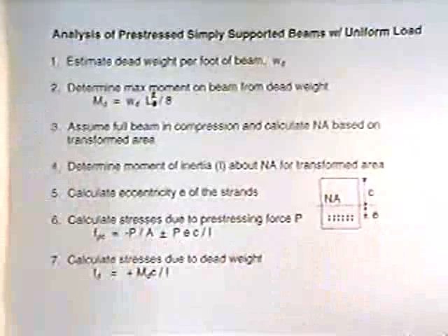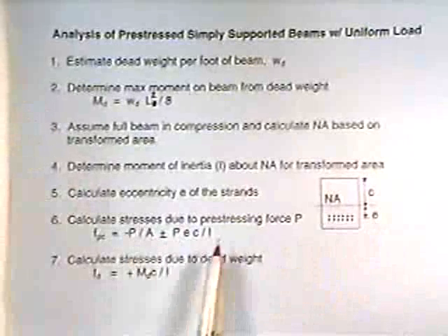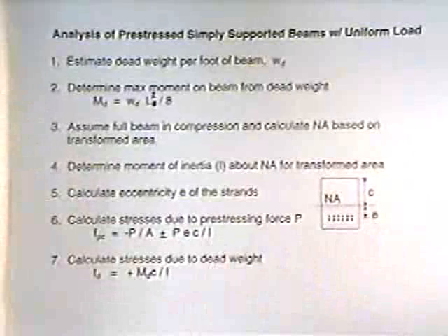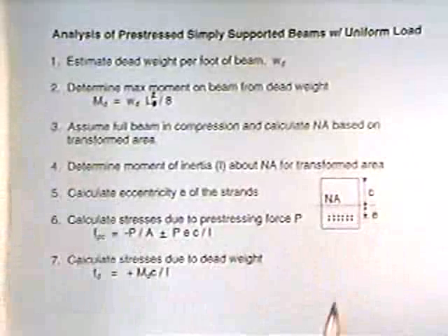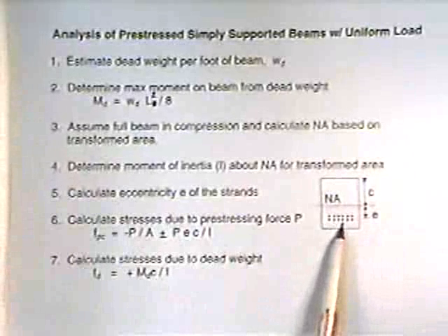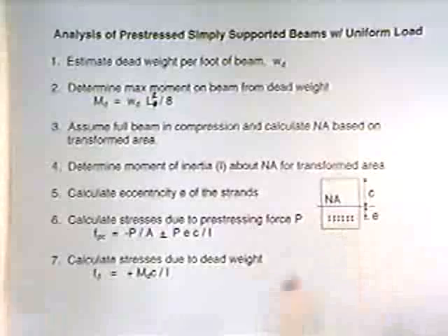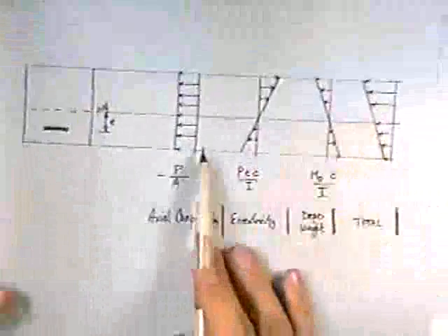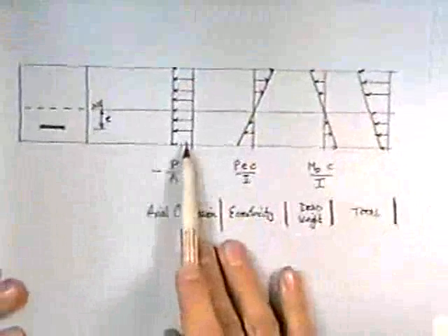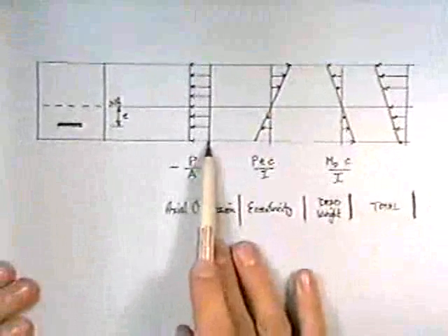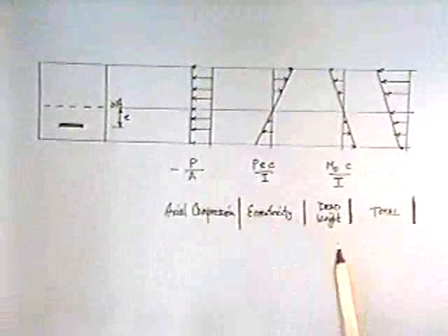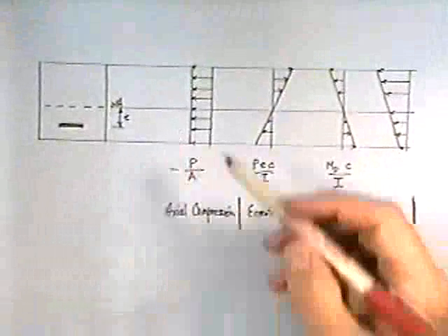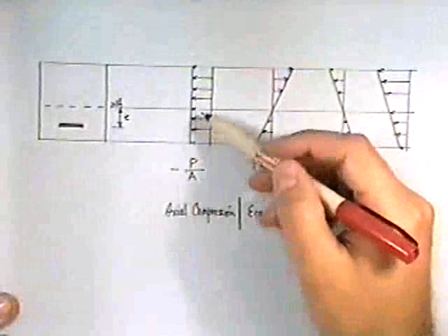Now what about stresses? The stresses that are going to occur are 3 of them. Just imagine that you post-tension these rods. What are these rods going to do? They're going to try and squeeze the concrete beam together, in a uniform distribution. You guys don't have this on your sheets. If you apply an axial compression force, what you're going to do is squeeze it together.